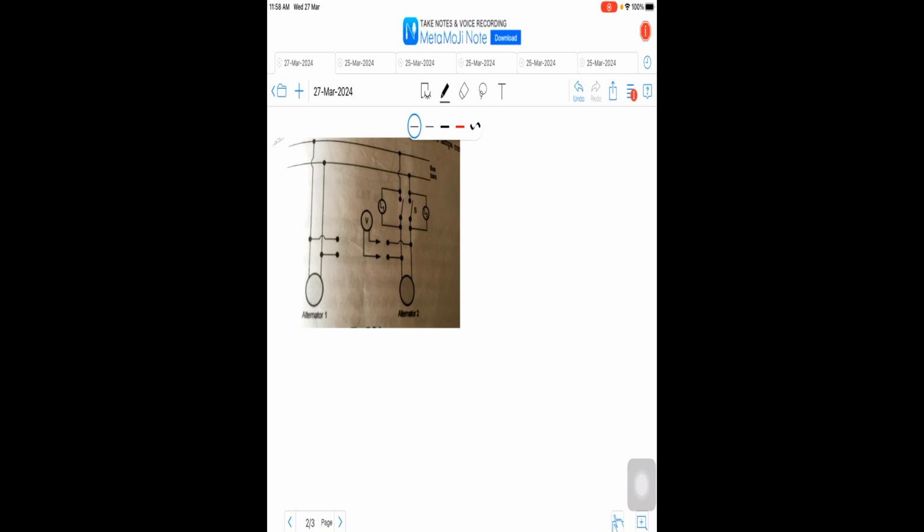Here the lamps remain at maximum brightness whenever there is no difference in the voltages of the two machines. With sharper and more accurate lamp brightness, we can achieve synchronization, because the glowing of the lamps is much more sensitive to changes in voltage at maximum brightness. So easily we will be able to achieve synchronization using the lamps bright method.